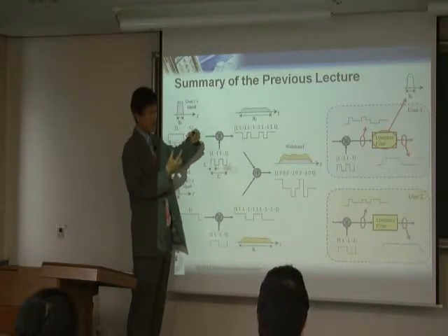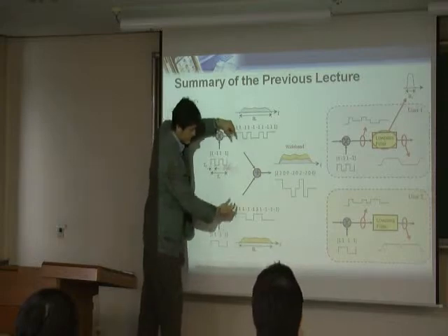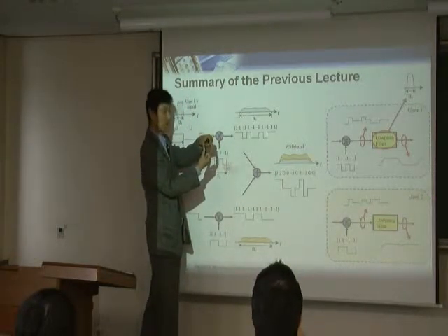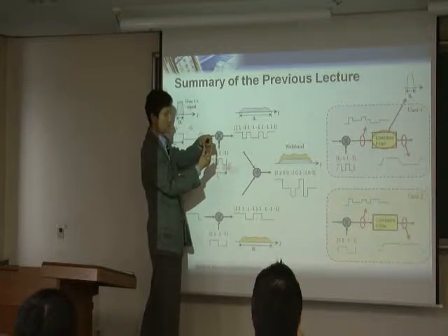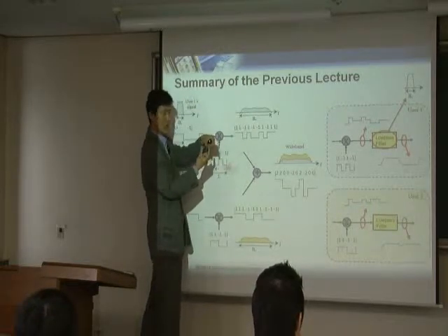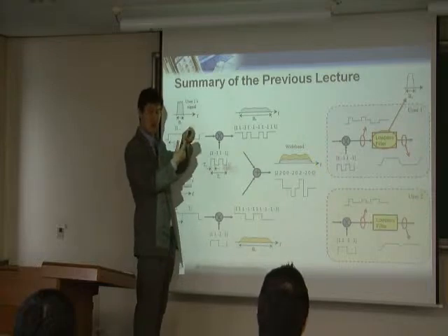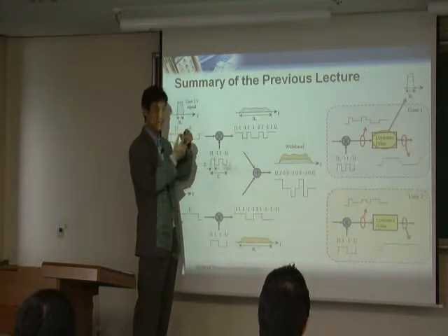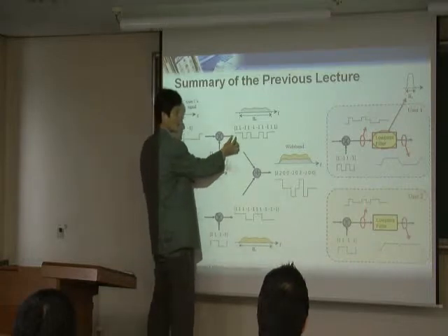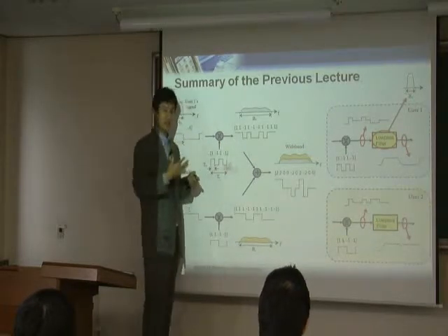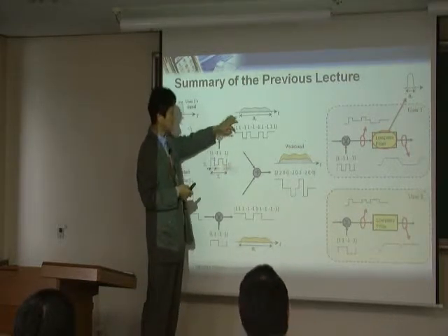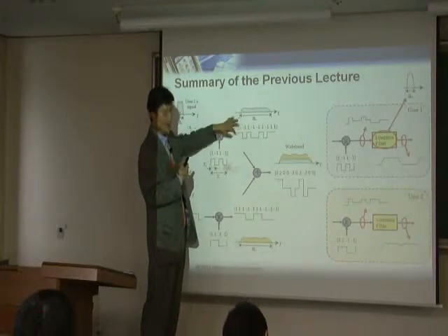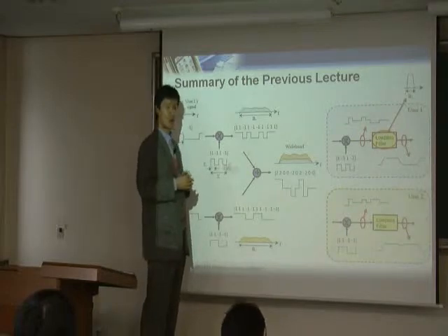The symbol boundaries are not exactly synchronized. Perfect synchronization is very unlikely. What is likely is that it's a little bit off. But when the two timings are off, that offset is less than one chip because of all this unexpected delay and multipath. That's what is likely happening, which may or may not cause a problem.